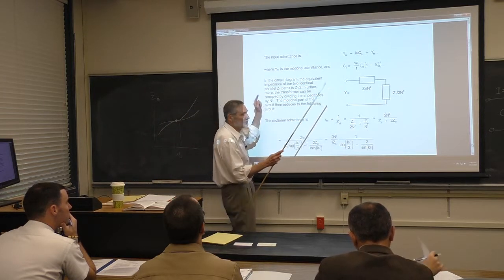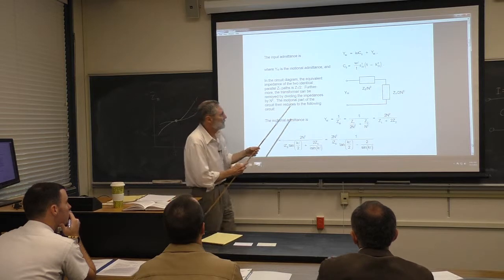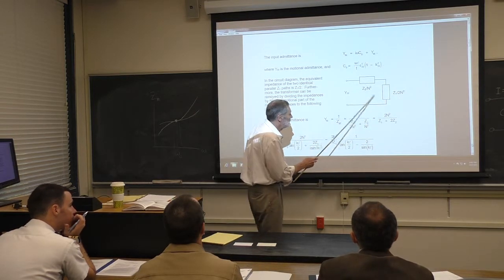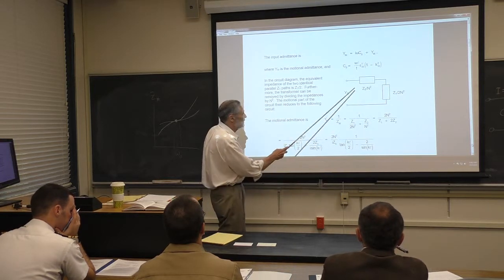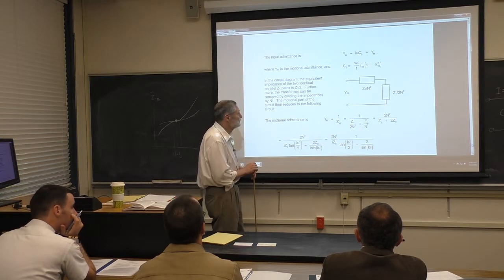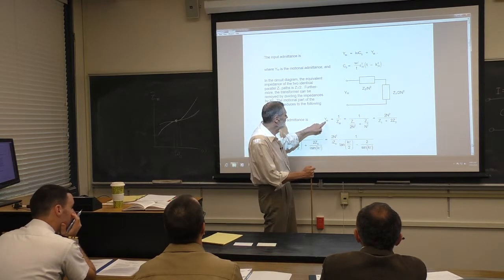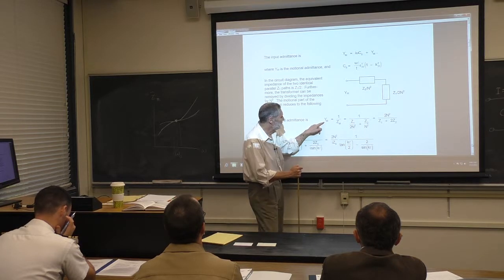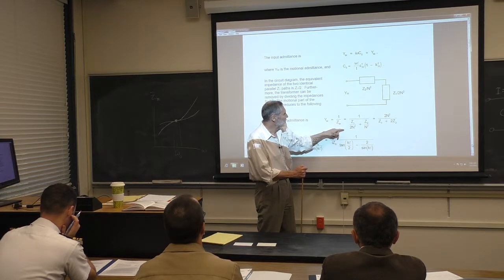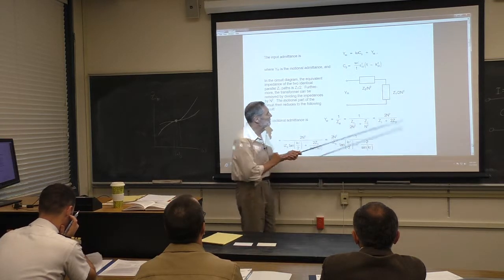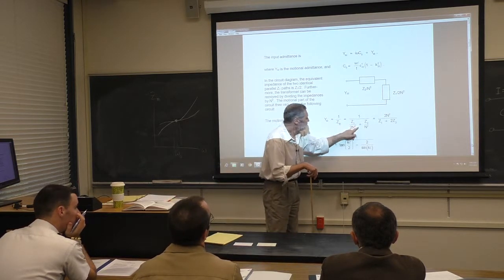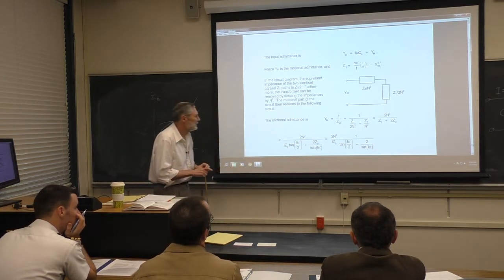Well, because we have symmetry, just like we were talking about before, the Z1 gets halved, and the Z2 stays there. And we get these two admittances in series, so they're going to add in reciprocal. So the motional admittance is going to be 1 over the motional impedance, and the motional impedance is the sum of the two. You'll notice I've eliminated the transformer here. That's why the n squareds are there. All right? So we can simplify this to that.